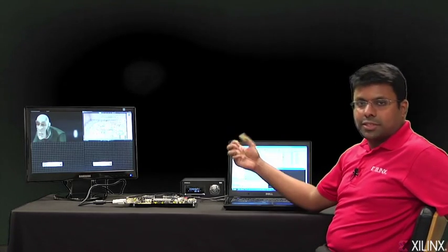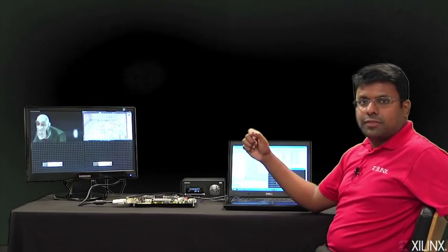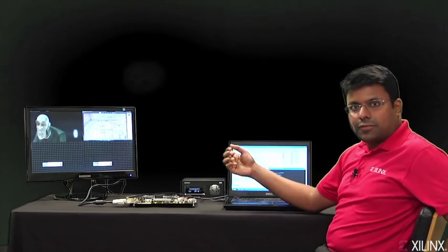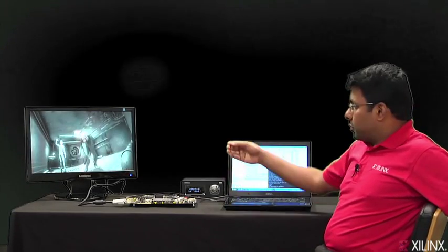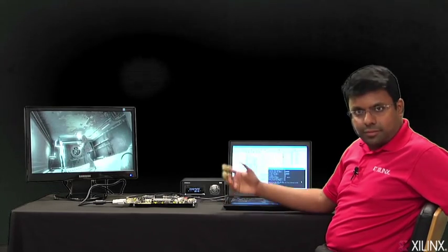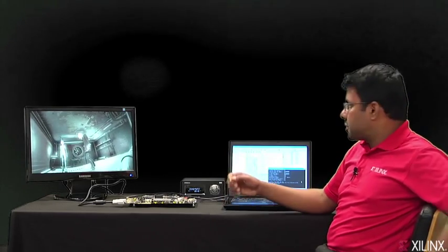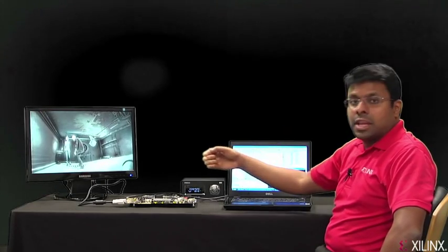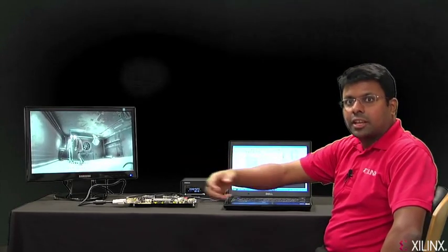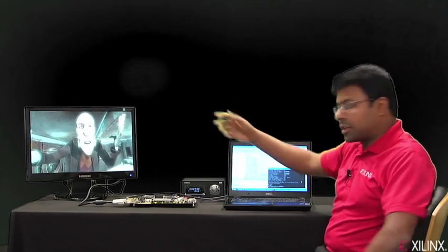Let's look at the same system for a broadcast high definition video application with AXI-4. Now I have the same system running with the AXI-4 design with multiple 1080p 60 video streams. As you can see, the first video input is fine. The system is able to bring it in, send it to memory through the AXI interconnect, read it back, so you can show it on the screen.